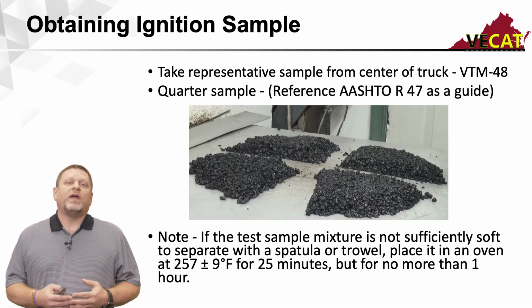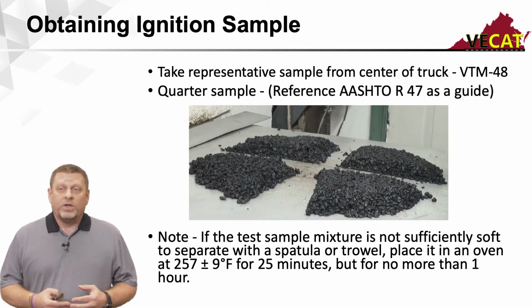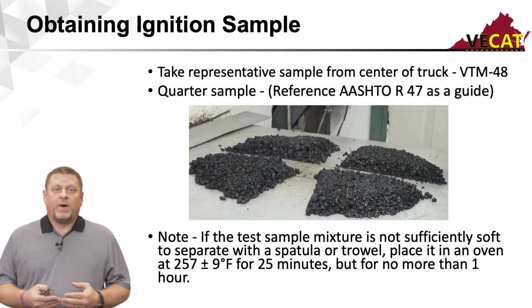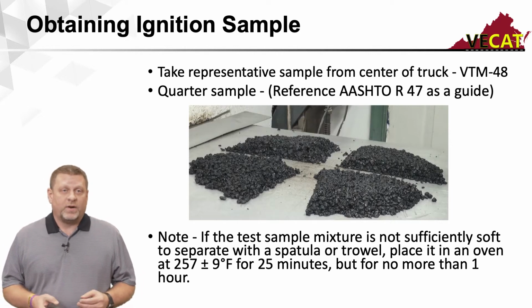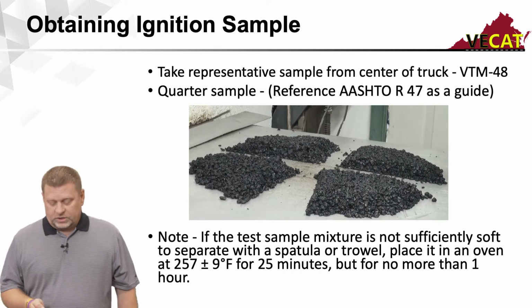The one thing you can't do is heat it more than 1 hour, or you may actually begin to lose some of the asphalt binder that would be part of your sample. So it's important to see that time and temperature range there for reheating ignition samples.